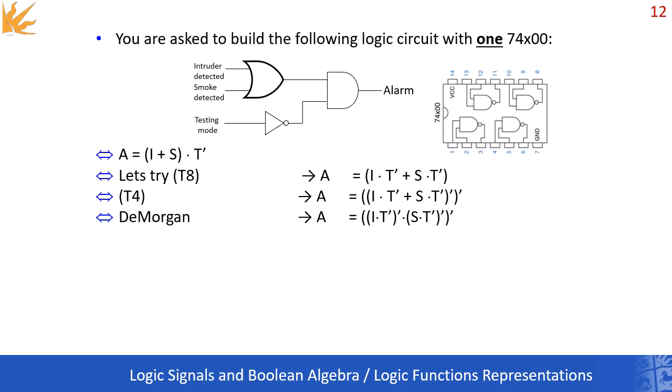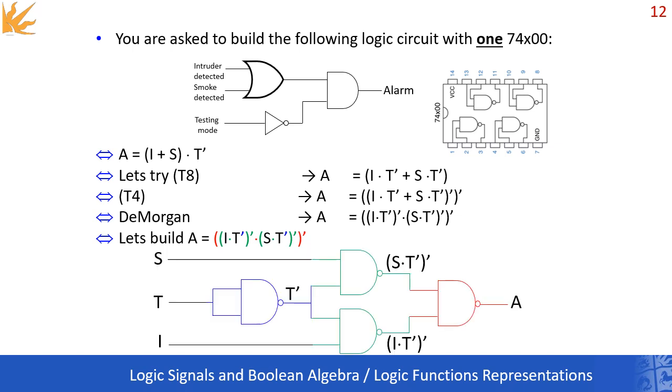And of course, we changed from an OR operation to an AND operation. So overall, we have a series of AND operations and a lot of inversions over here. So with far fewer steps, by using more theorems, not just De Morgan, we ended up in this implementation that has only NAND gates implied.